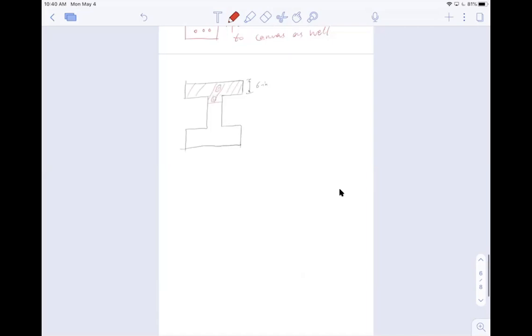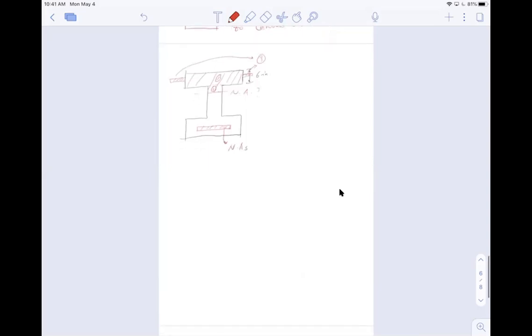For the sake of argument, I am not going to include this little wing part, which is actually from the compression reinforcement. Let's call it 3. You can include it, but all I'm saying is you have a cracked section and you don't know where the neutral axis is. That's the question. And this is the bottom reinforcement right here, which is calculated already, and you know this is nAs. So assuming I have a distance,